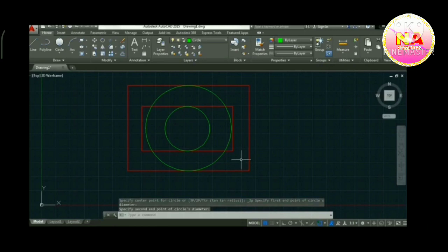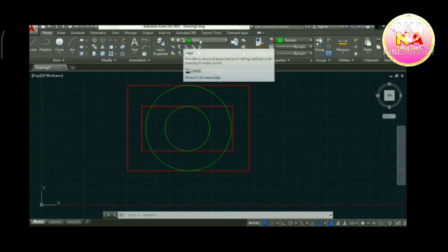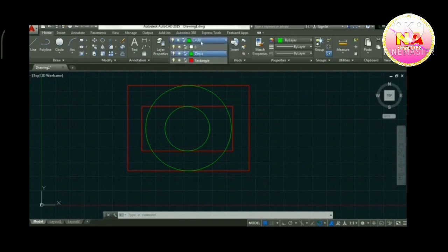Now if someone asks you that he wants only the drawing or printout of the circle, what do you do? Because you have already drawn the circle and the rectangle in one workspace, but you can't give him this drawing. So for that there is an option. You can turn off your layer, so it will just be invisible for you.